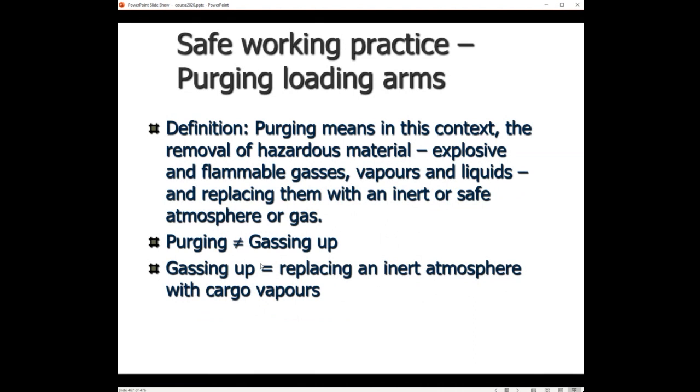Then the purging of the loading arms. We have the purging before and the purging after the operation. In this context, it means that you should remove the hazardous material and replace it with an inert or safe atmosphere. That is after the operation, before you disconnect it.